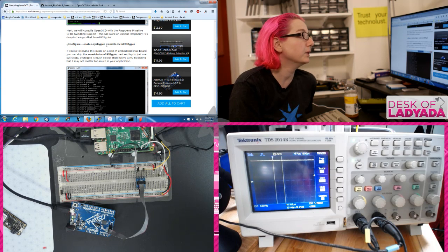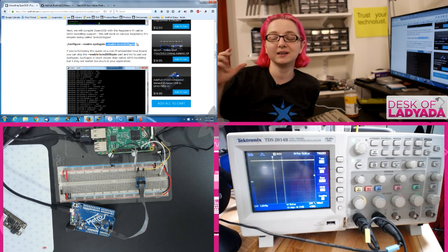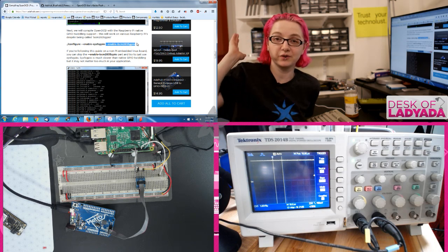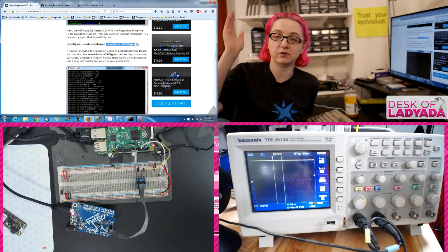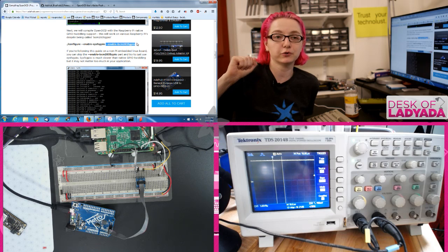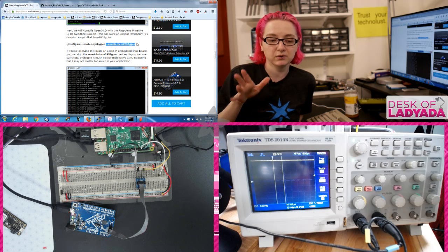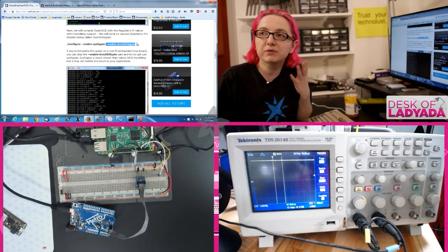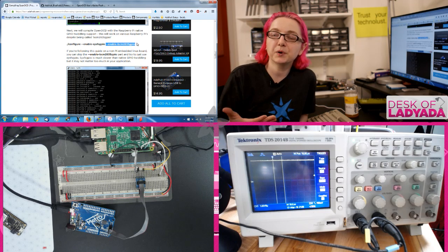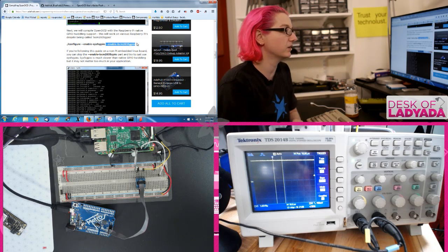And then with enable BCM2835 GPIO, what's cool about this is it actually memory maps the peripheral for GPIO and just writes the register. It just sets the bit, clears the bit, sets the output, clears the output directly, so you get ultra fast. You have to set the timings to tweak it because if you overclock it, you're going to change the I/O speed. You'll have to figure out what I/O speed you need for your chip to get really fast programming, but not so fast that you don't program properly and you miss some of the bit transitions.